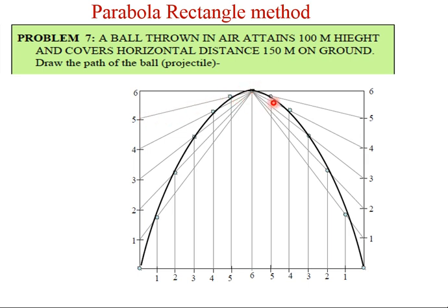In this similar way here, a vertical line will be drawn through 5 and it will be intersecting with A5. Again, a vertical line will be drawn through 4, intersecting with A4. A vertical line drawn through 3 will be intersecting with A3, and in the similar manner A2 and A1. Whatever intersecting points you get here, P1, P2, P3, P4, P5, P6, P7, P8, P9, P10, draw a smooth curve with free hand and then make it fair with the help of a French curve